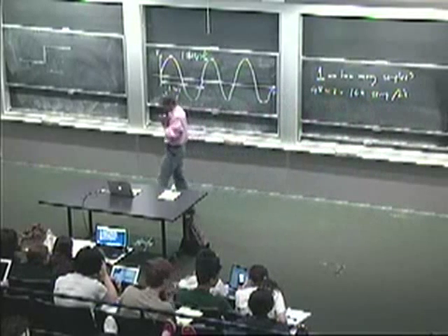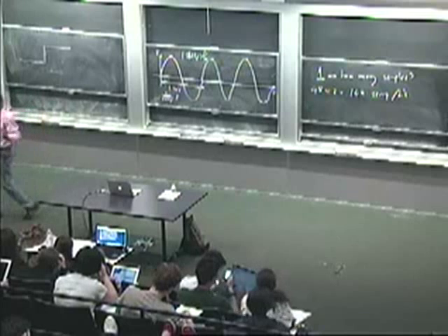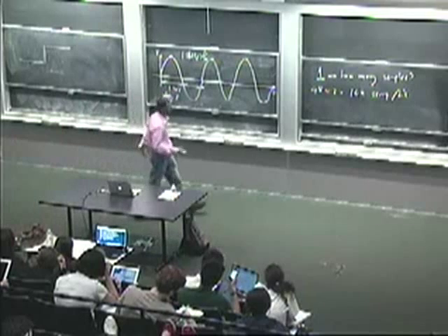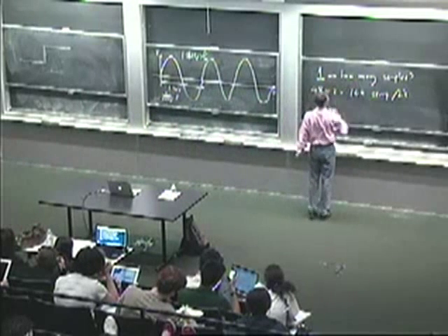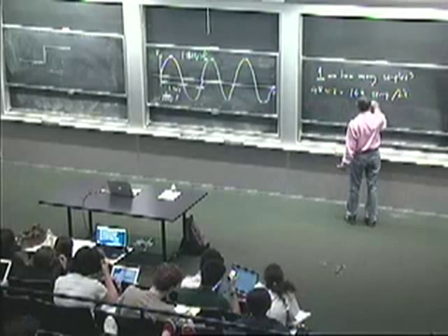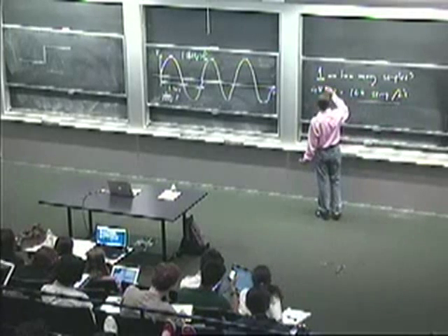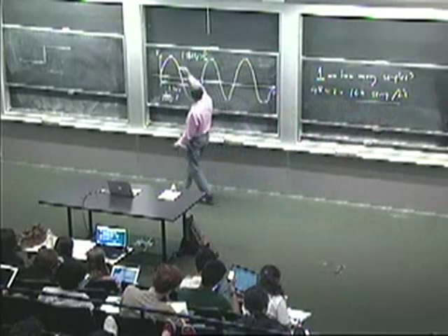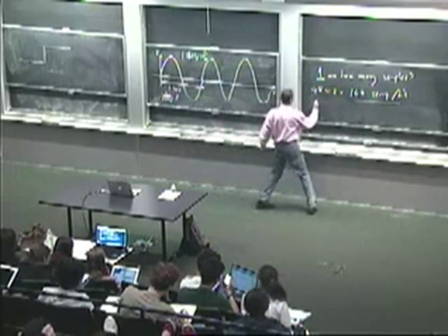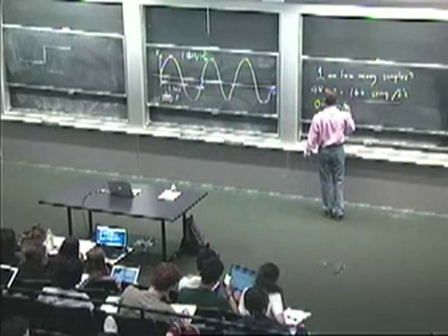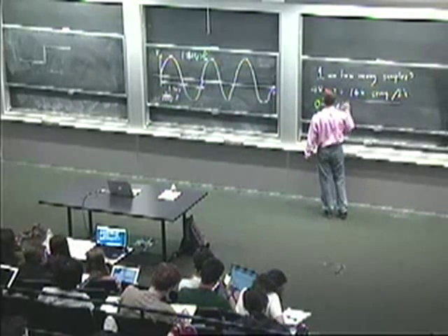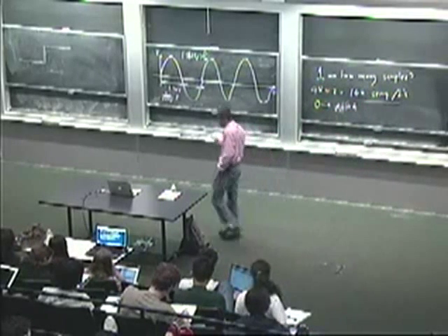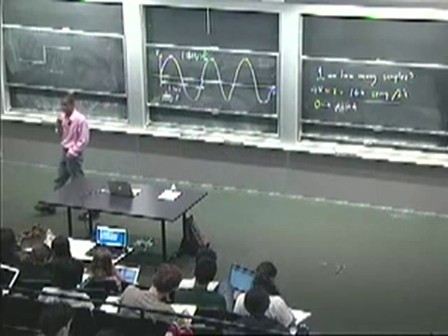Now, to transmit a 0, I could do a bunch of different things. I could decide to keep the channel silent. If I do that, it's called on-off keying, and that's what we're using here. So we're sending 1 as, if we decide to use 144 samples per bit, then it means we represent a 1 as 144 samples, which corresponds to 3 of these. And then we represent a 0 as nothing. So we don't send anything. This is called on-off keying, because we send on for 1, where we send a sinusoid, and for sending a 0 bit, we send nothing.